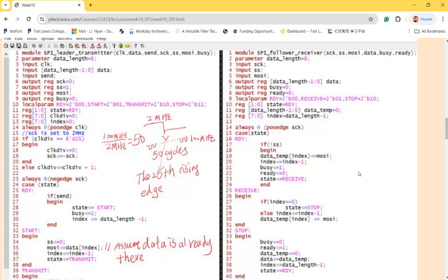Why does this matter? You can program it, and after you synthesize it and put it on the FPGA, it's already configured. It's not fabricated, it's already on the hardware. You cannot change it, right? However, if you interface this with Arduino SPI, if the Arduino has a built-in SPI, you have to configure the registers to make it run in the right mode in order to communicate with your ASIC, which is the application-specific IC designed on the FPGA. So this is a part of the course project.